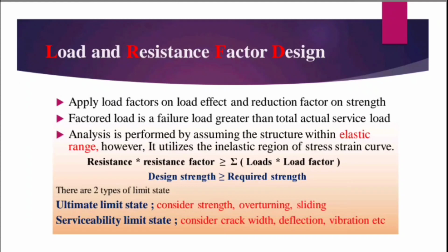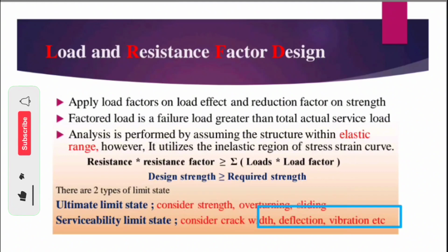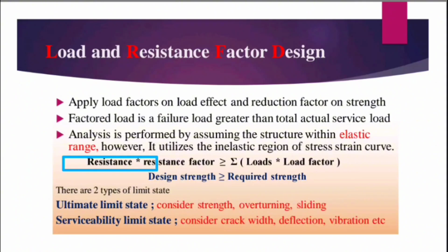And serviceability considers the crack width, deflection and vibration. It does not allow the member to vibrate beyond its tolerable limit. So it covers both serviceability and safety. Remember one thing: the strength reduction factor is always less than unity, and the load factor might be equal to 1 or greater than unity.